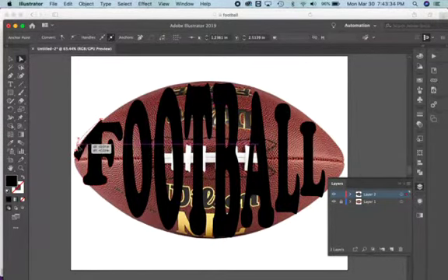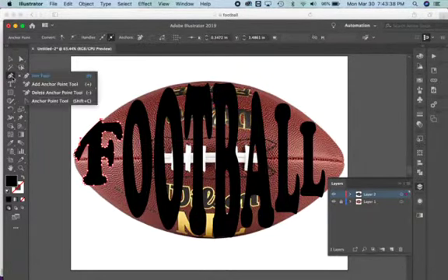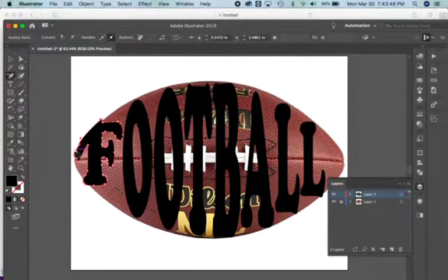Alright, maybe I'll use my delete anchor point tool. If I click on my pen tool and hold it down, it'll give me some options to delete anchor points. I'm going to delete a couple of these anchor points because they're a little redundant and unnecessary, and they're not helping to fit the shape that I'm going for.